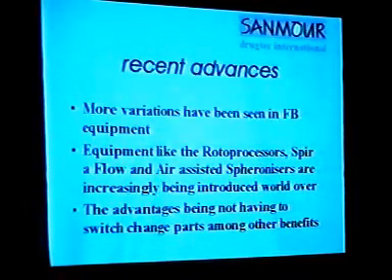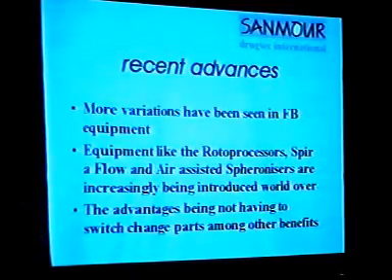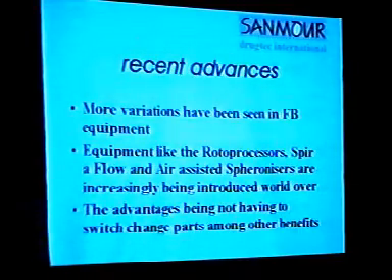More variations have been seen in this fluid bed equipment as well. Now you have latest versions like the rotoprocessors, spiraflows, and assisted spheronizers. Now these are being increasingly introduced the world over. The advantage being that you don't even have change parts. Like you don't have to change from top spray to a bottom spray, take the product out, then put your change part, then again load your product in. This is a sort of a built-in all. It has a disc, it has fluidization, it has tangential spray, it has the bottom spray and everything. And without removing the product from the processor, one can shift from one spray mode to another.